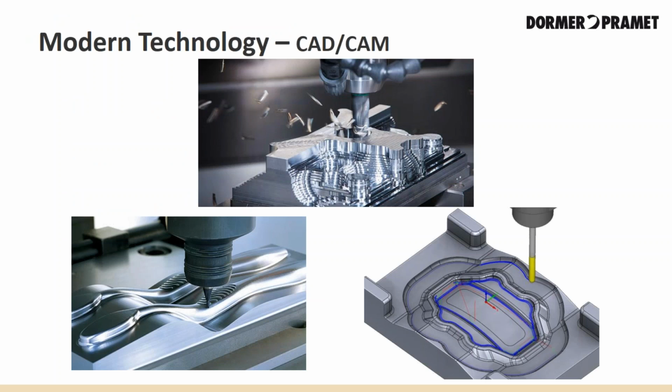One of the biggest challenges for CAD/CAM is to create toolpaths with small step-overs at very high feed rates. Techniques are being implemented into CAD/CAM to optimize the toolpath and to take advantage of high-speed machining. Techniques such as remaining stock acknowledgement after roughing, dealing with internal sharp corners, auto reduction of feed in the look-ahead mode, and methods such as trochoidal or slicing. Let's look at these last two.